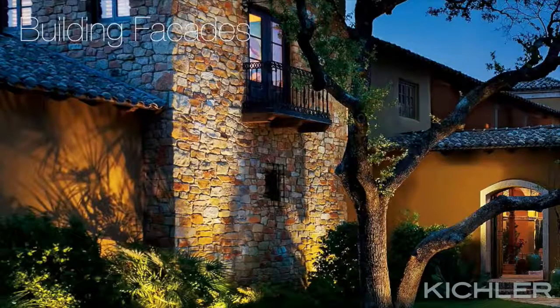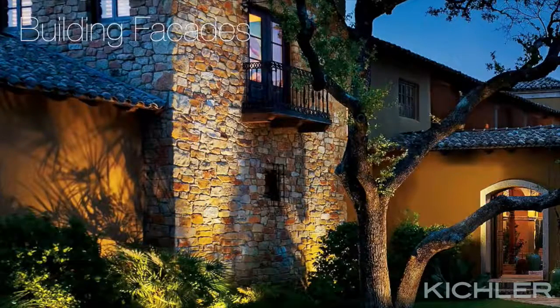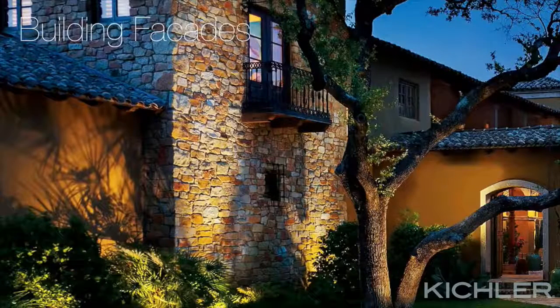Less textured surfaces can be made more dramatic through shadowing effects from the landscaping in front of a wall. Less textured surfaces also do well with the softer, more even illumination of a wall wash. Remember that materials will also affect the luminance, or reflected light, visible from a position in the landscape. If you want a darker surface like brick to appear as bright as a white painted column in front of it, the brick will require significantly more illuminance than the column.